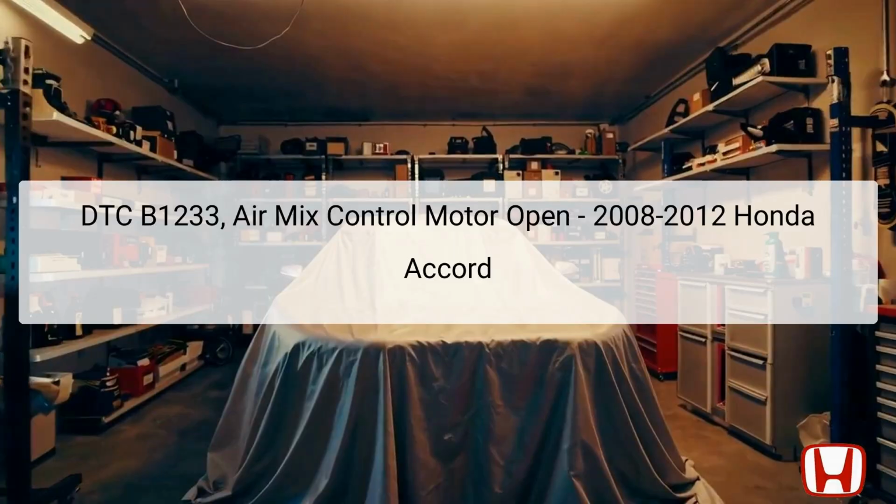The Diagnostic Trouble Code, DTC B1233, indicates an issue with the air mix control motor circuit in the Honda Accord models from 2008 to 2012. Specifically, this error suggests that there is an open in the circuit of the driver's air mix control motor, which is responsible for regulating the temperature of air entering the cabin. This issue can result in improper temperature control, affecting the overall comfort of the vehicle's interior.